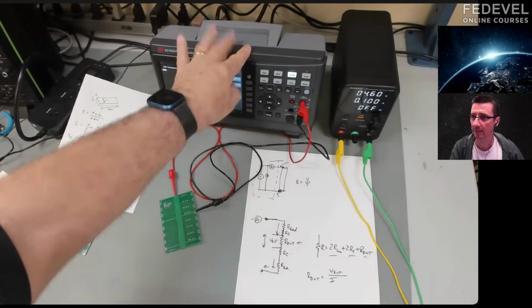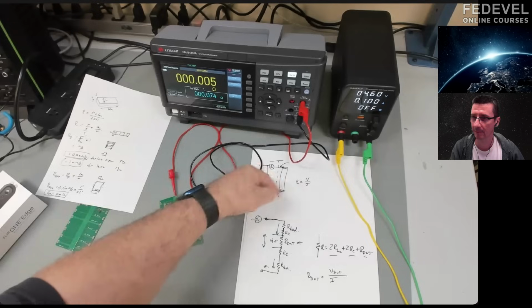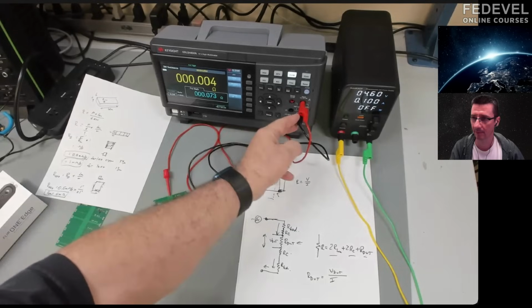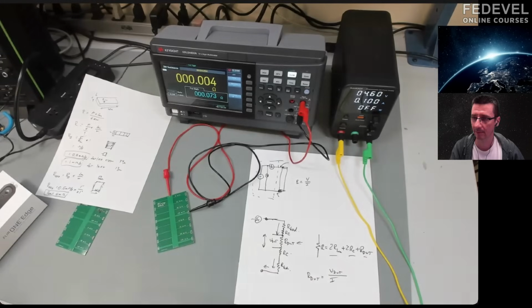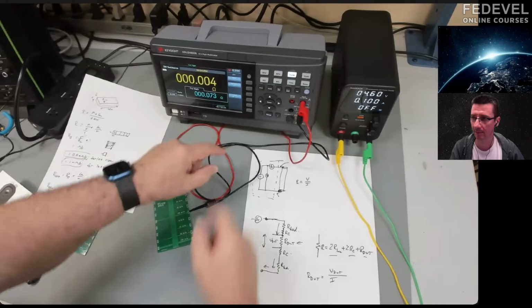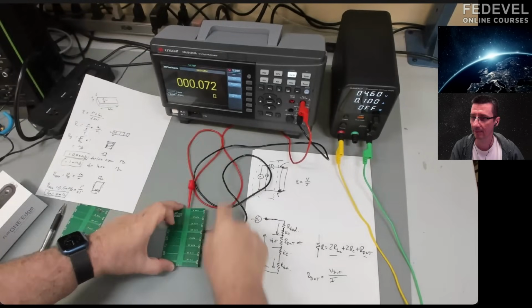And to do that, we're going to use the digital multimeter. This is going to drive the current. There's an ammeter on the inside. It's going to measure that current. And these two probes are going to measure the voltage across the wire. So I'm going to turn off the null. We don't need that anymore. We go back to the resistance.